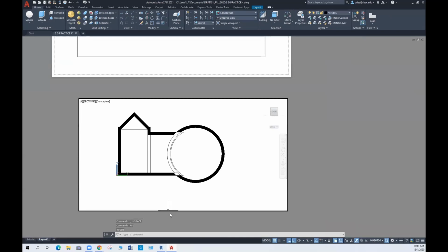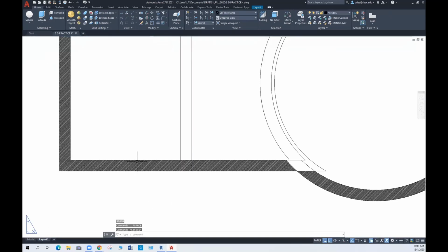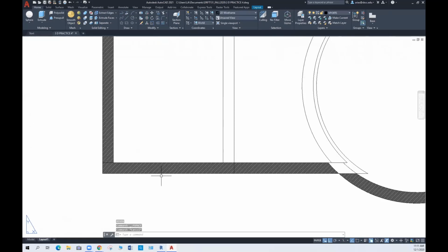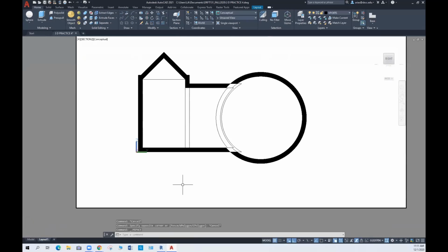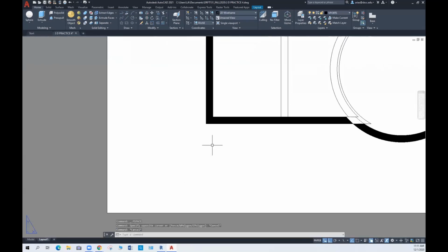So obviously, the outline, the hatch is very dense. That's why it looks like that. Let's see if I can modify the line type scale. Maybe do it 12. What did I do? MSLT scale 0, PSLT scale 0, and region. Okay, nothing there yet. So let's do LT scale again to 1 and region.